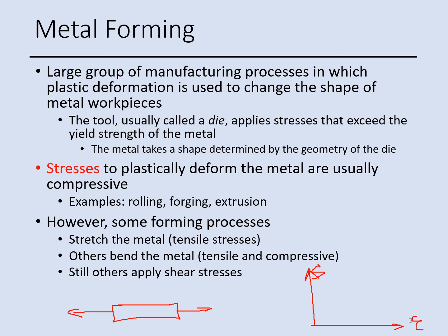What happens because of that pulling? We have stresses in the part. As we pull apart, we have some elongation, then we have some stresses. And normally, for metal, we get this type of stress-strain curve. As you see, up to a certain point, we have a linear plot. Linear means it's a straight line. And up to some point. After that point, we have a nonlinear curvature.